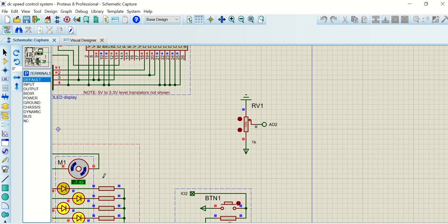So what you can understand from the flowchart is that we have taken a very small delay time, 100 milliseconds. That's the reason why the drastic change in motor speed has occurred. If you take a longer delay time, let's say in seconds, if you increase it, then the transition will happen over a very long amount of time. So you can see the fixed value is around minus 7.45 or something like that.